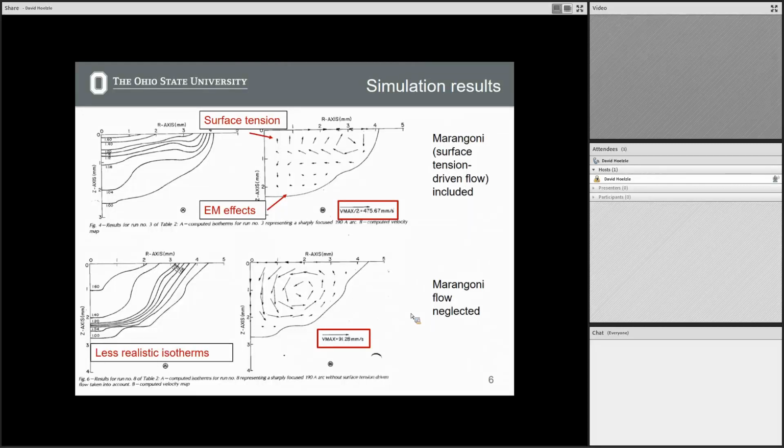Right here. Well, because you have one region of flow that's doing this, right? We have another region of flow that's doing this, right? And so there's a stagnation point right here. And what's happening with the stagnation point is, say this is our metal A, and this is our metal B. The point of a weld is to make the AB alloy everywhere in the weld. That's obviously not going to happen if no material is flowing.